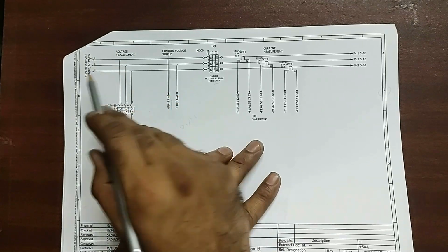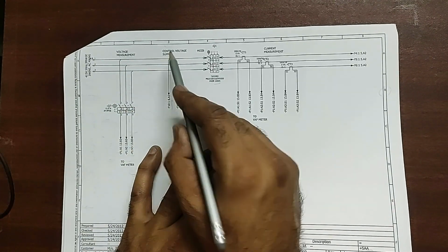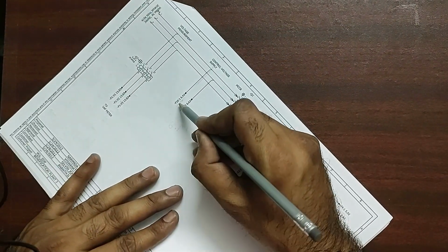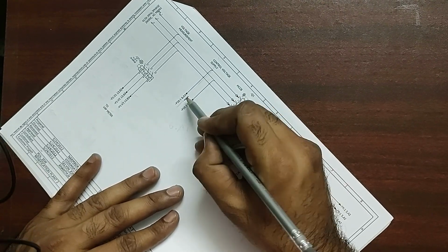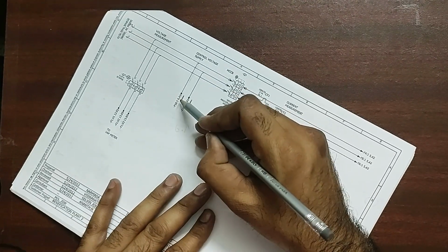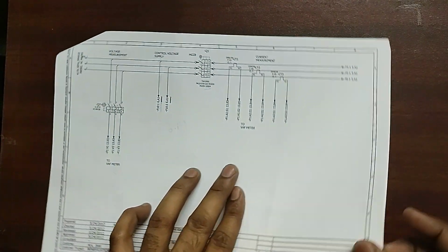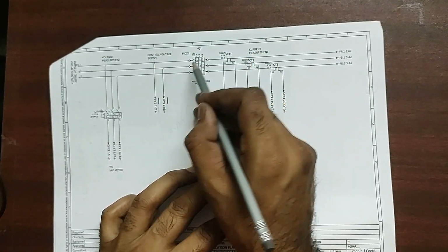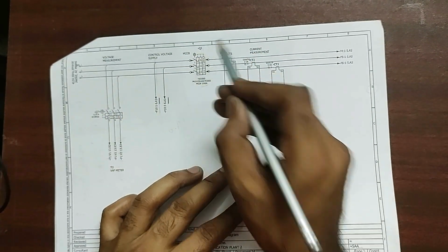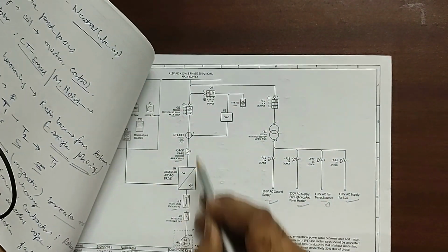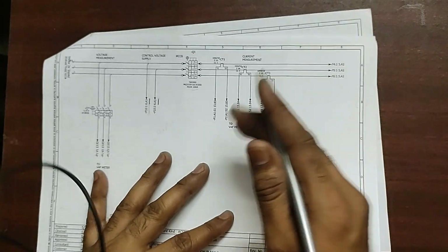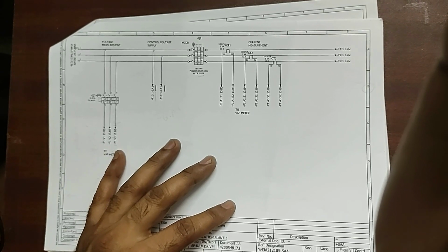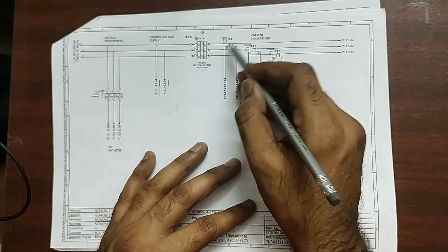This is the main supply, 415 volt. Again, for control supply, we are getting the tapping here. For example, if you want to see how it has been done, here you can see 6.A1. So this is 6. Okay, we'll check in the next page. This is control supply. Next, MCCB from the previous page, Q1, this one. Once it has been on,